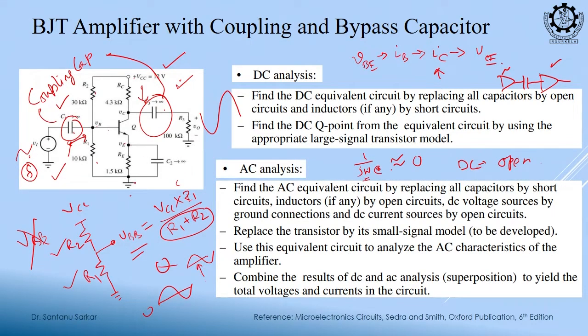Now, what is this cap doing? See, this is not coupling with something, is there any source? No. If this is an AC signal, then this capacitor will be like a short circuit. So, should this resistance be there or not? It should be short, right. So, if it is short, what is this potential then? Then you will think like this is my ground, right. Okay. You see what we are doing. If we have this emitter resistance, this is our ground, right, but this potential is our IE-RE.